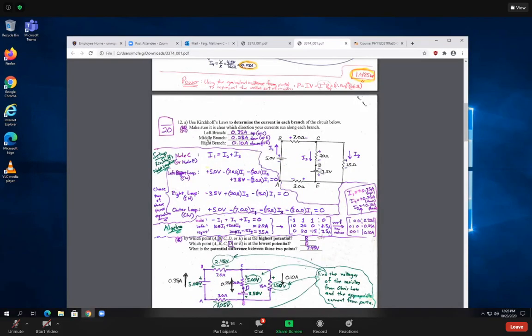So it's not telling me the voltage at C is 5 volts. It's not telling me the voltage at D is 5 volts. It's saying the voltage step across that resistor is a change of 5 volts. So you really want to kind of have that idea clear in your head. Is this a voltage at a point? Probably not, but it could be depending on how you use the terminology. It's probably a voltage across an element or between 2 points.